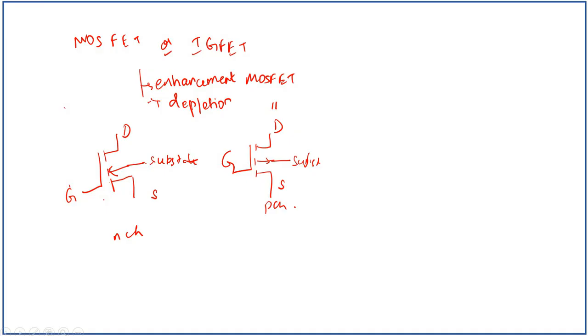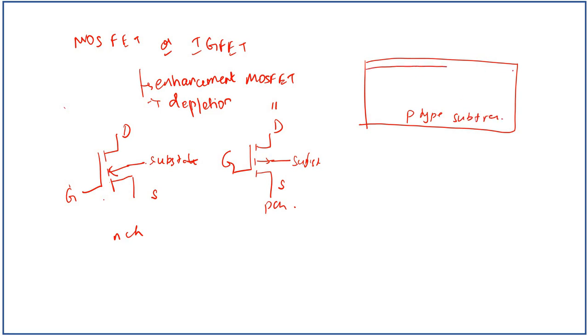So the construction of MOSFET is like, we have a P type substrate, and here an N plus region and an N plus region, and there is a channel like this here. So here we have the connection for gate, an aluminium region and the gate connection. Here we have the connection for source, and from this N region the connection for the drain.